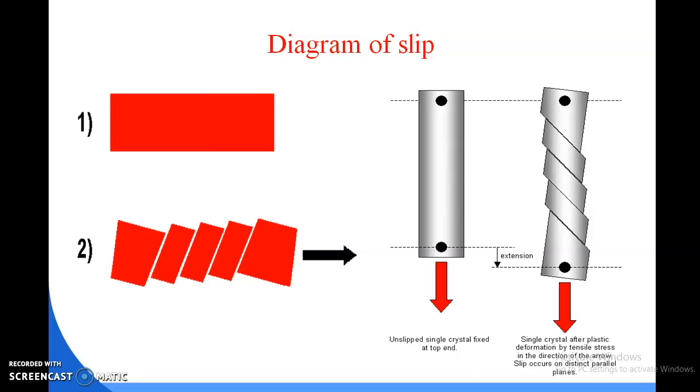A slip plane and a slip direction constitute a slip system, and a critical shear stress is required to initiate a slip. The reason behind slip is shear stress. Slip is an important mode of deformation mechanism in crystals. For metals and technically used metallic alloys, it is by far the most important deformation mechanism and is subject to current research in material systems.